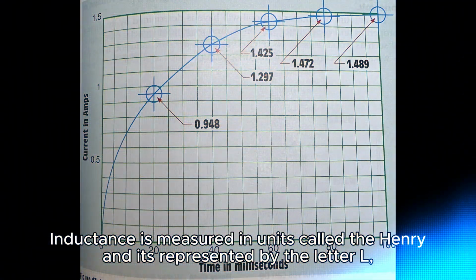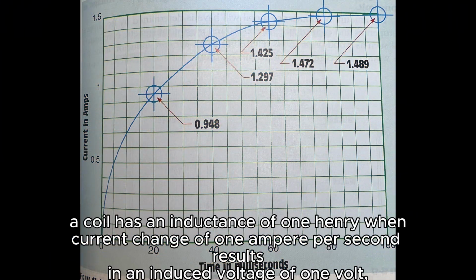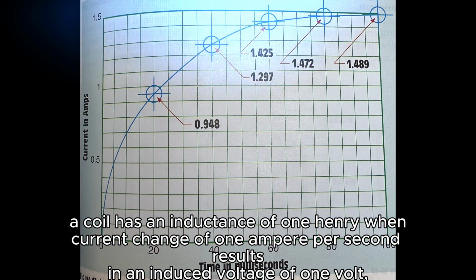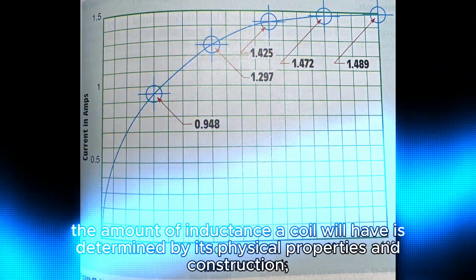Inductance. Inductance is measured in units called the Henry and is represented by the letter L. A coil has an inductance of 1 Henry when a current change of 1 ampere per second results in an induced voltage of 1 volt. The amount of inductance a coil will have is determined by its physical properties and construction.